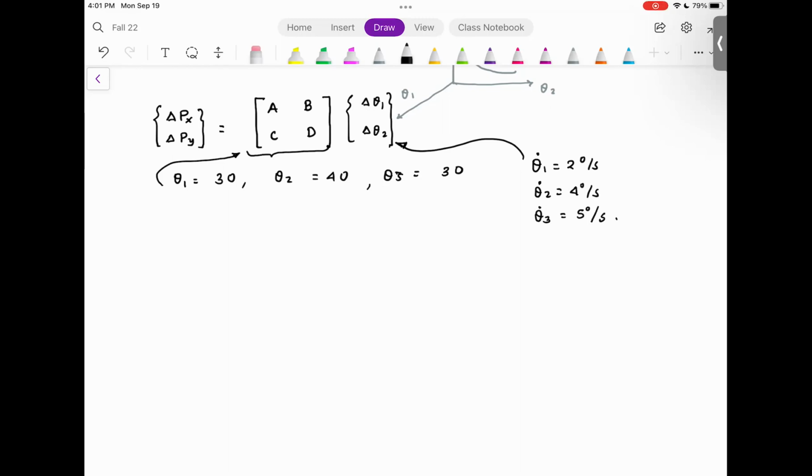How do we determine our joint velocities? So joint velocities will be given to you. Or the other way to do that is, imagine a 3D printer. You are trying to 3D print something. So feed and speed is dictated by the application. Based on those feeds and speeds of the end effector, you will find your joint velocities. That's why your 3D printer stepper motor sometimes moves fast, sometimes moves slow. Because the application demands certain feeds and speeds, and the joint velocities are calculated to achieve those desired feeds and speeds. So you have to solve that inverse problem multiple times. Any other question before I go to the next part?